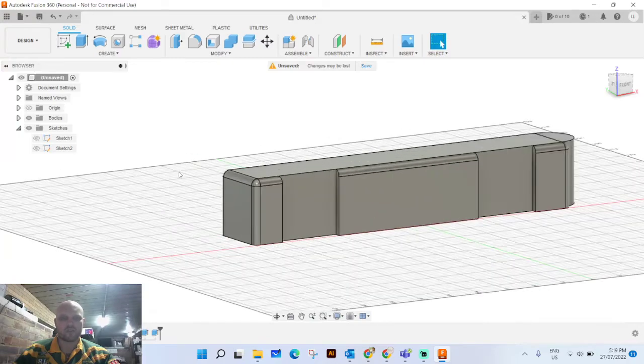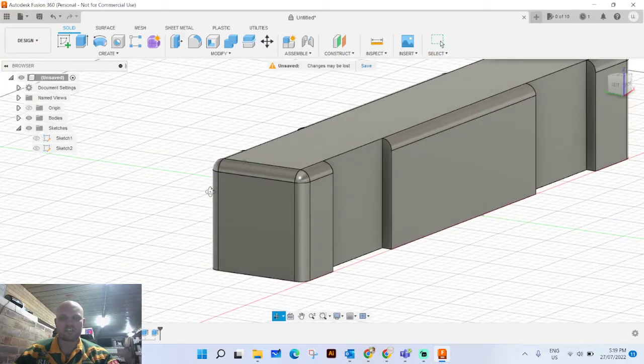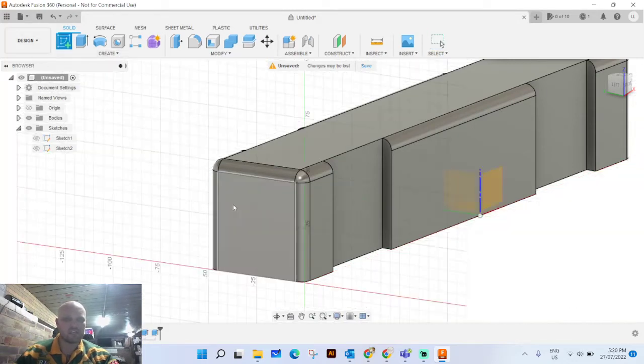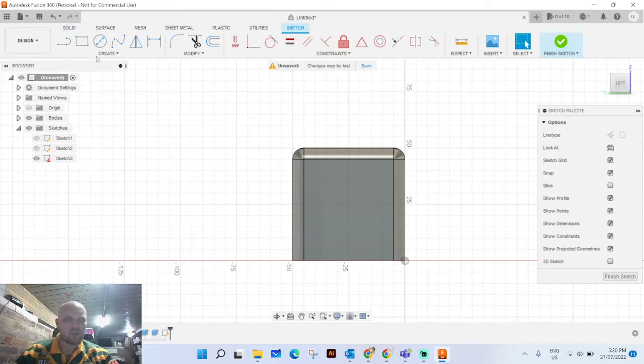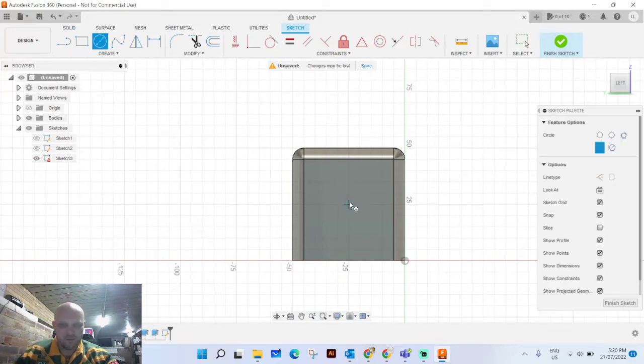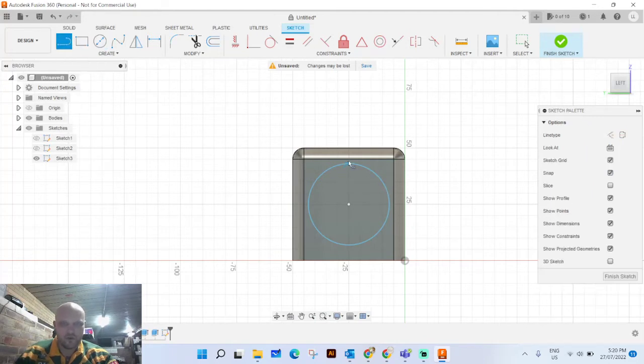So I'm going to zoom in on the rear section of our car. We need to put a sketch on the rear section. So let's create a sketch on this face, and we want to get right around the center of this section. We want to create a place center point, a circle, and I'm also going to put in 2 lines, just cutting right down this central section.